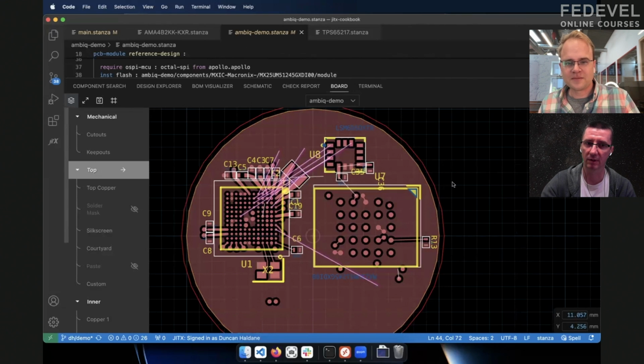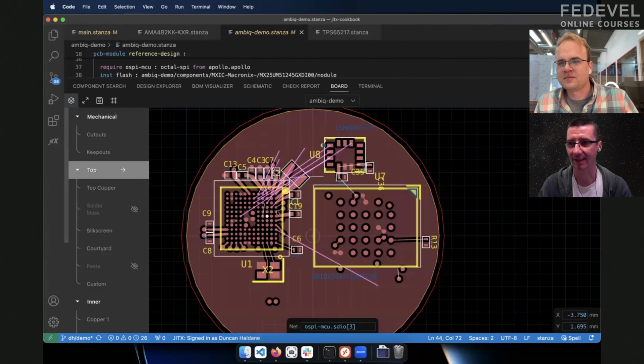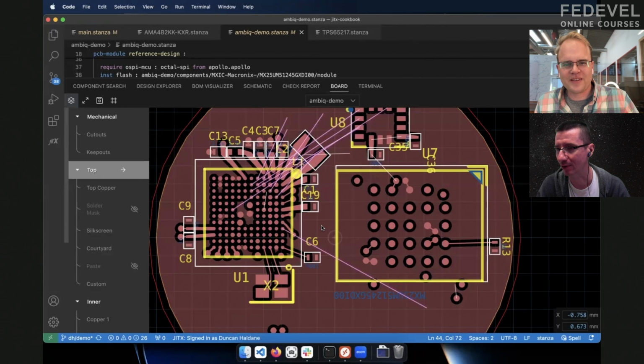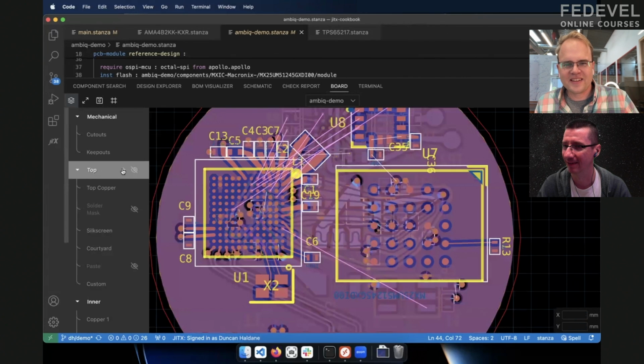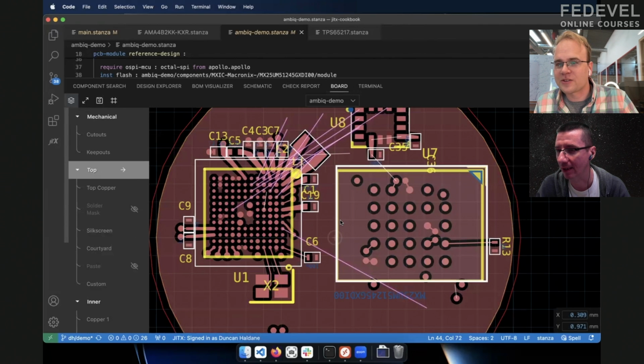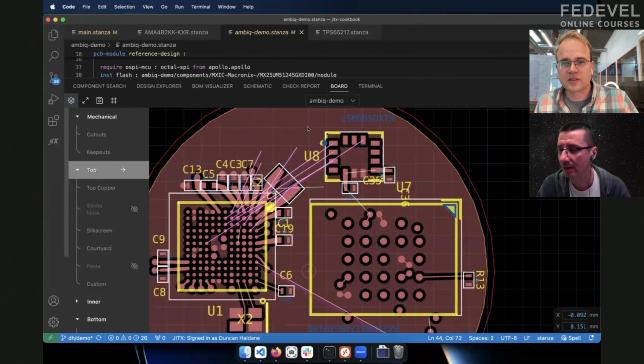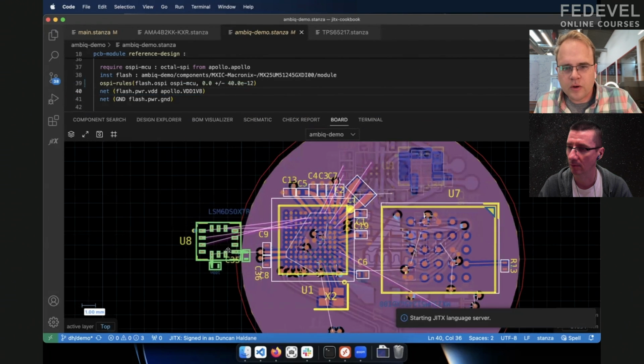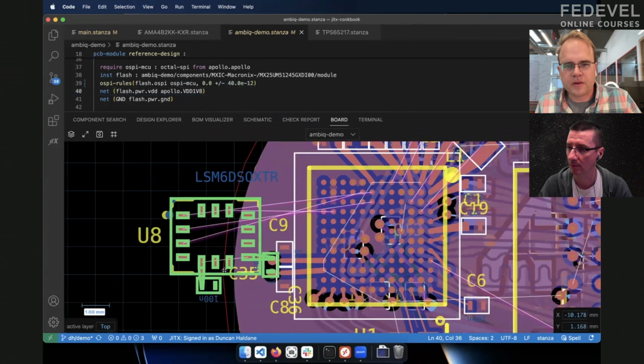Okay, because even if you can place these on 4 layers maybe, I think it will be super hard to have good reference planes for the signals, because it's going to be broken. So I think I'm doing okay so far. Here at top I have ground, and that's my reference for OctoSPI. Bottom, there's not really much there yet. But I think you're right. Let's see if we can make it work. So here's the gyroscope. We were over here for our pin assignment, right?